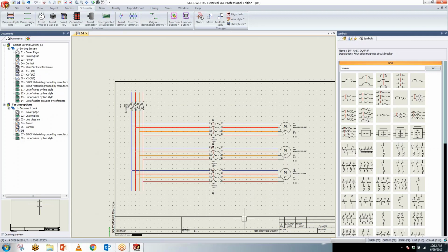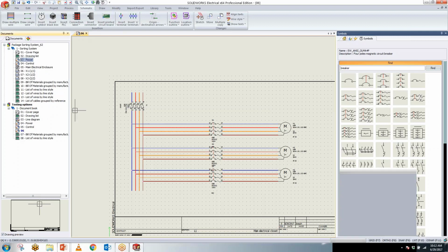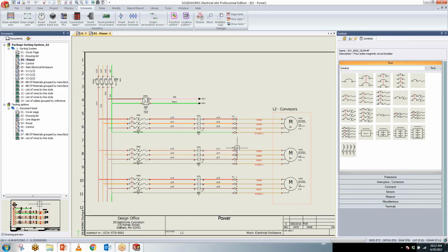So something simple looking as such, in less than an hour, will end up looking like this schematic. So this is a full schematic that has all the components that I was trying to explain in that example. Whether it's motors, disconnectors, every single component in this schematic is functional. And what I mean by functional, guys, is on top of the fact that we went ahead and assigned manufacturer properties, each component has its own rating, whether it's power, voltage, amperage, you name it. And that's going to help us down the road to check for errors in our schematic.